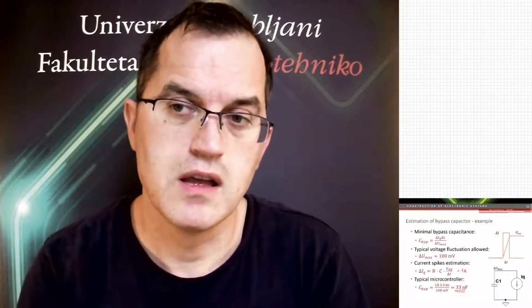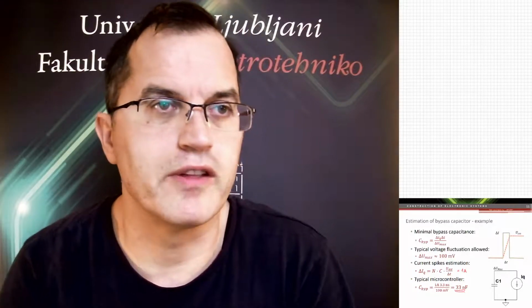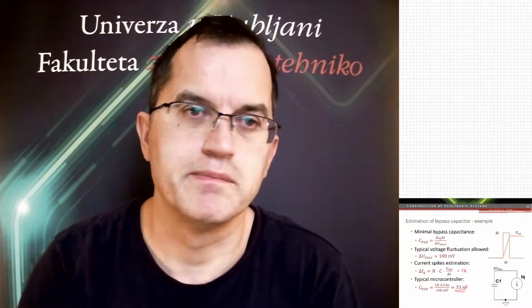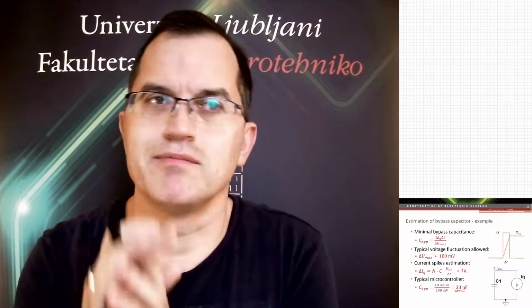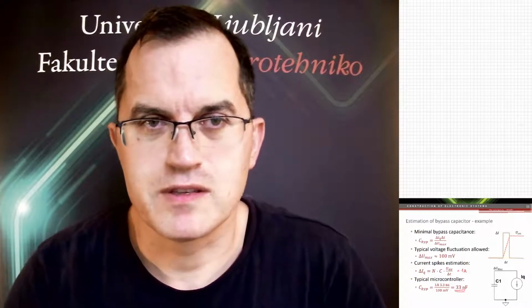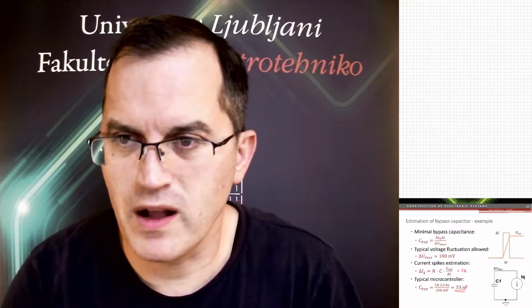And of course, the obvious answer would be 100 nano. We all put that and we don't ask. We just put them, and if it works, we don't care. 100 nano is like a golden standard for all the bypass capacitors. Of course, that's just in the wildest approximation.